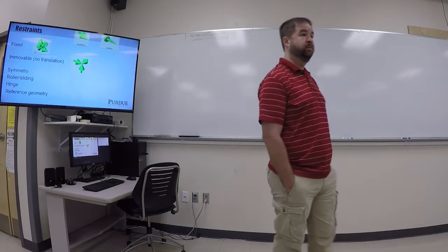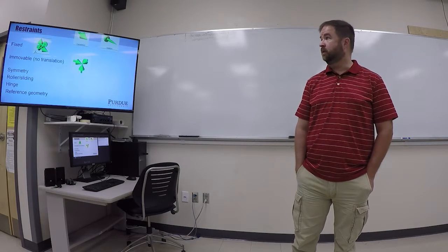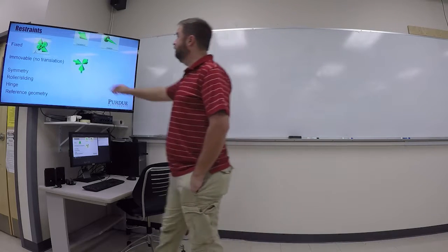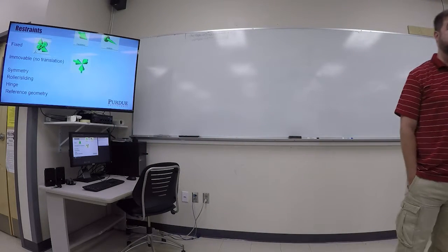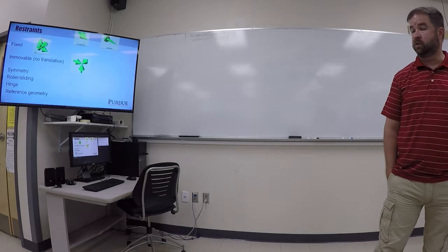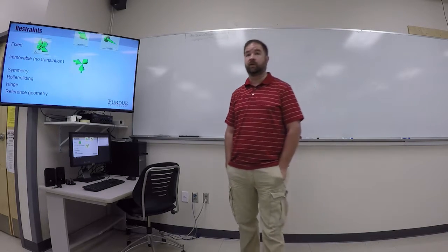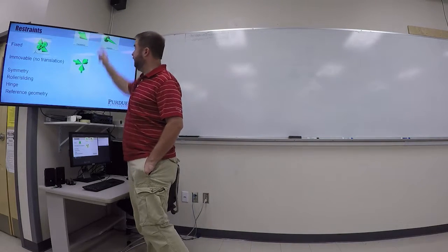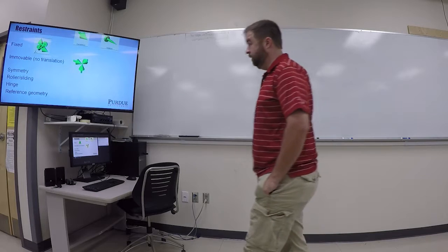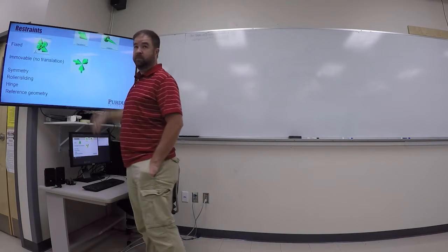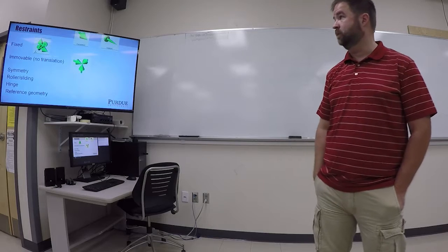When we have something that is preventing movement, you have control in SolidWorks to set that up. In graphics in SolidWorks, it looks like an arrowhead if translation is prevented. So if you want to keep it from moving in the X, Y, or Z directions, it should look like an arrowhead. If you want to prevent a rotation from occurring, like it's fixed in the ground, then the rotations look like tails. And if you have both of them restrained, then it has the arrowhead on the front and the tail on the back. Both of those combine together to tell you that you have translation and rotation both restricted.